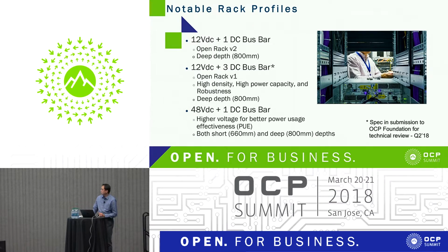Then a quick review of those major profiles. The 12-volt DC plus 1 DC bus bar is compliant with the Open Rack standard V2 and with the deep depth. The 12-volt DC with 3 DC bus bars is V1, which Penguin is still using. It provides high density, high power capacity, and robustness.